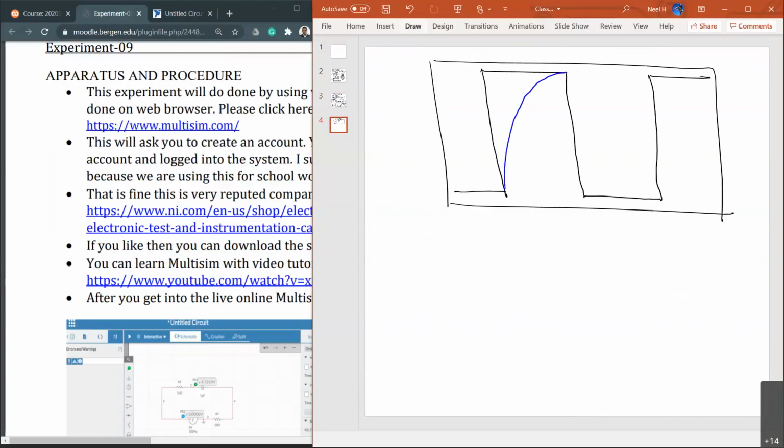So this is actually charging the capacitor. And whenever you switch off, the capacitor will not go directly to 0 voltage. Instead, it already has a certain amount of charge, right? Because of that, it's going to take some time to decrease. So it's going to show you these nice charging and discharging curves on your oscilloscope.